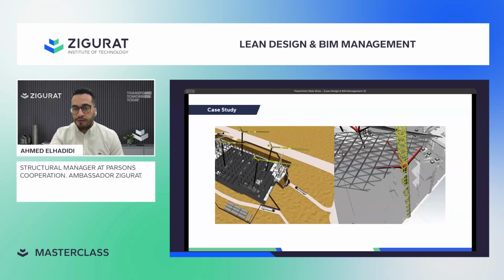I don't have any plan to implement this. After you finish the design and the above designer finishes and gives you the model to do the coordination, you will find this error. There is a steel shading or something that clashes with the tower crane location. And this tower crane location is a temporary location, by the way. It will not continue with you in the project. So you can move it around and check the mobilization plan to find a correct location.